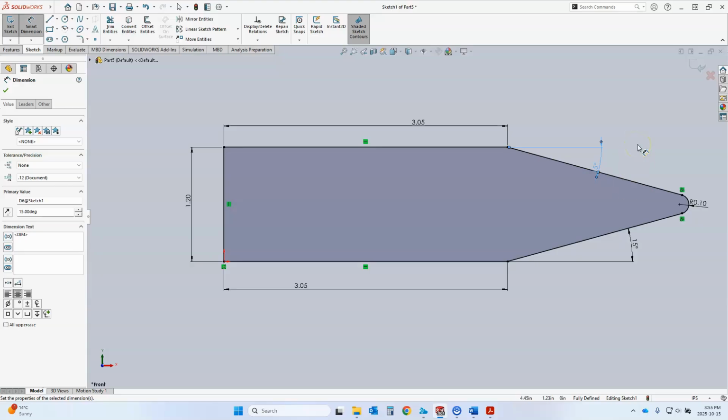Great. So at this point, we're basically done dimensioning our part. I can also see that this whole outline is now changed to being black. And down here, I can see that it says fully defined. So what that means is that this drawing is not looking for any more information from me. I've got all the information input to create this shape as accurately as possible.